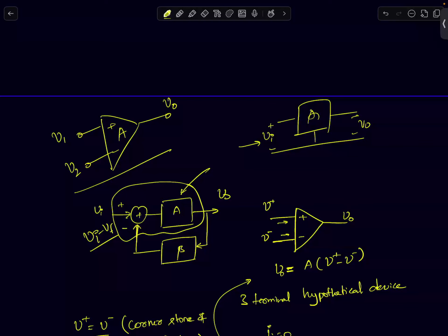In this course, it will be called an opamp. But let's call it an extremely high gain amplifier. This is a hypothetical device where A is much greater than 1. It's going to amplify the difference between the 2 signals. Okay. If you have this device, I will show now that you can build a wide array of interesting circuits using the idea of negative feedback.